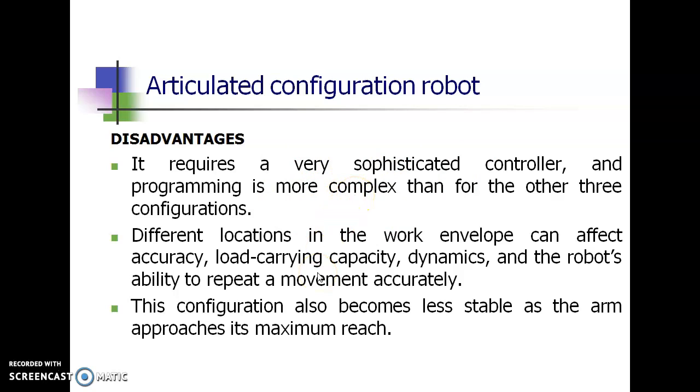And one more thing is different locations in the work envelope can affect the accuracy, load carrying capacity as well as repeatability. So all these three, accuracy, repeatability and load carrying capacity, are getting affected, or they depend upon the locations and are going to vary.